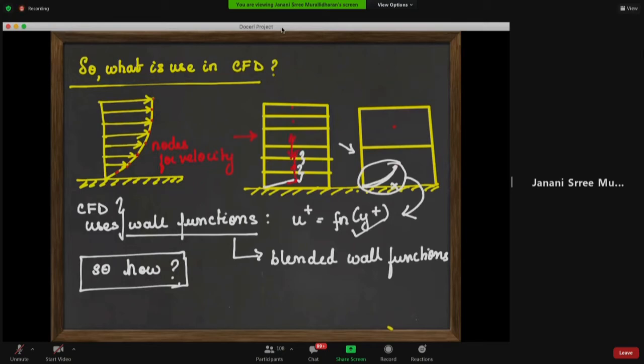The downside of this is your eddies vary in scale to a large extent, right from very, very small eddies to large vortical structures the size of your pipe. Okay. So if you're going to try and capture these small eddies, you end up with a very, very refined mesh, which will stop you from simulating this in a timely manner. Okay, it's not practical. You're going into a DNS simulation, direct numerical simulation.